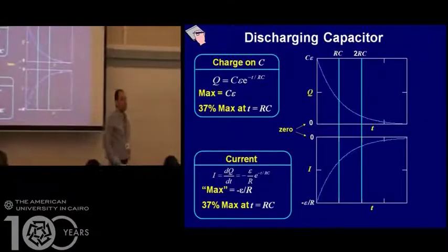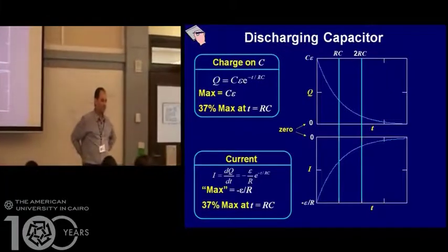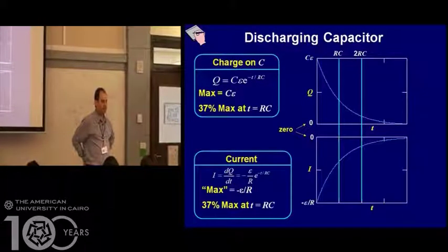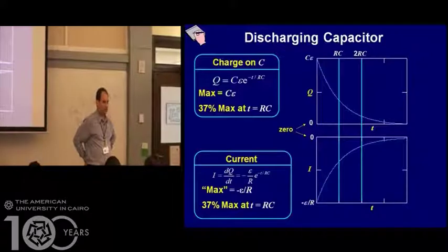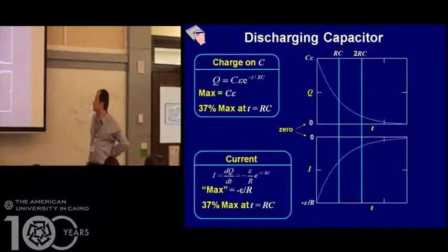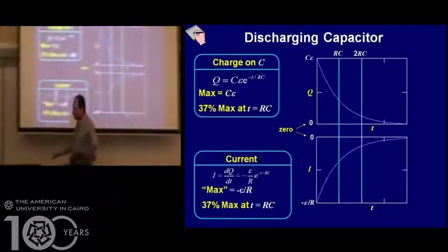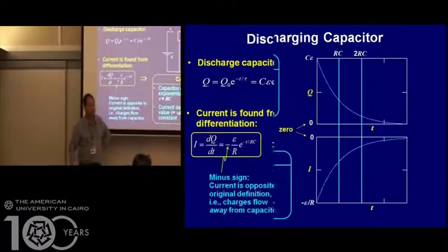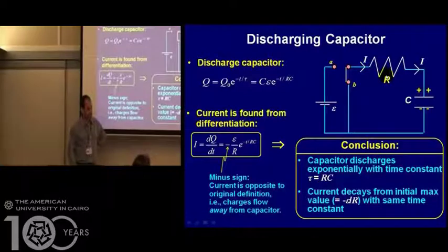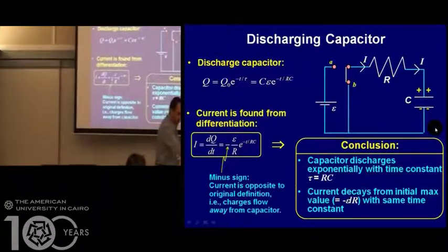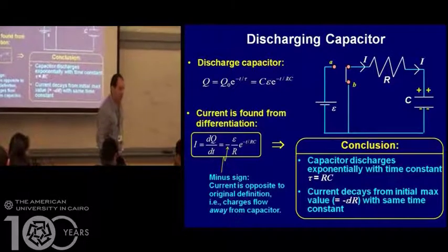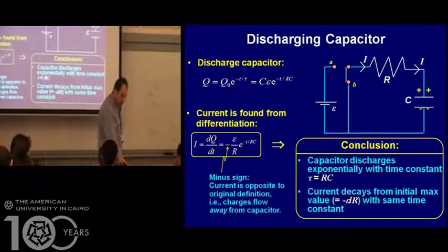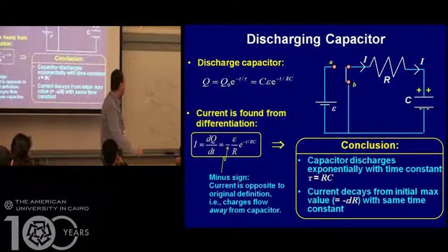Let's assume that R is equal to 100 ohm, C is equal to some value. So RC has a specific value here, but it's constant in any graph. For any circuit, you have to choose a resistor and a capacitor, and they have to have values. So if I know those values, after time equal to R multiplied by C, you can simply find what will be the charge after that time.